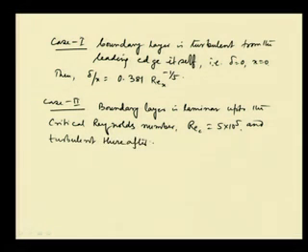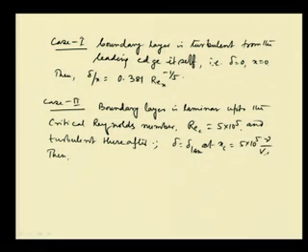Okay. Then what we have, the integration can be from delta laminar to delta. Under this situation, delta is equal to delta laminar, which is at x critical, and that is equal to 5 into 10 to the power 5 into nu by V infinity.